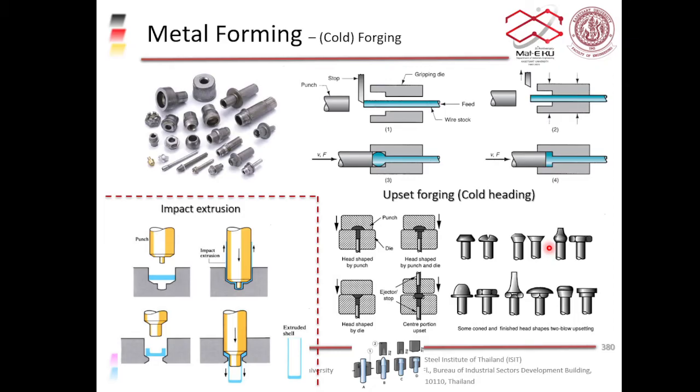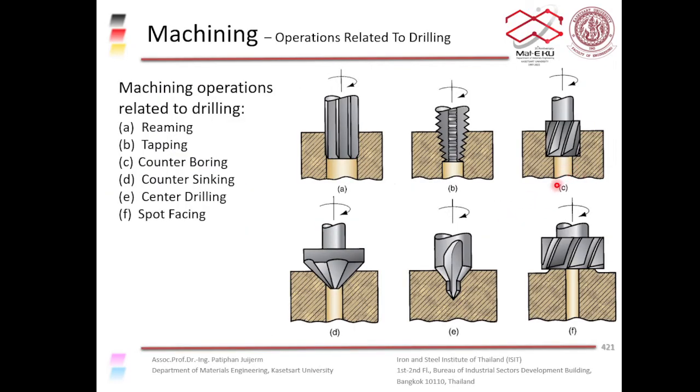So basically, countersinking and counterboring serve the same purpose, but because the shapes of the bolts or screws are different, we use different tools to produce the appropriate hole, right, between counterboring and countersinking.